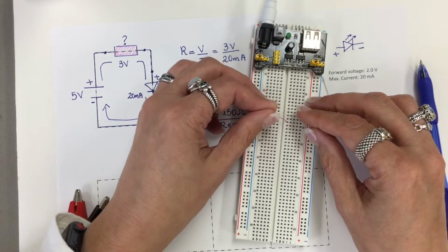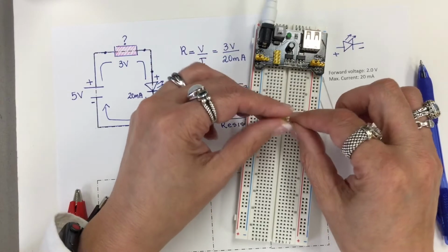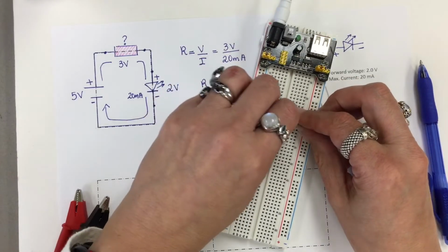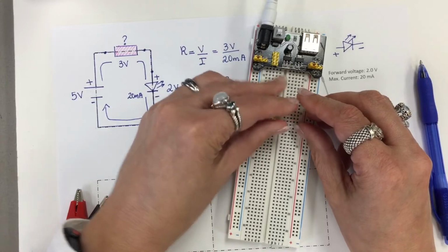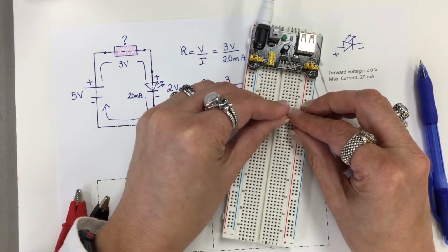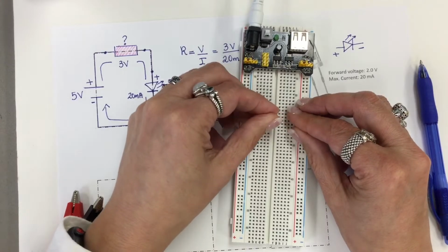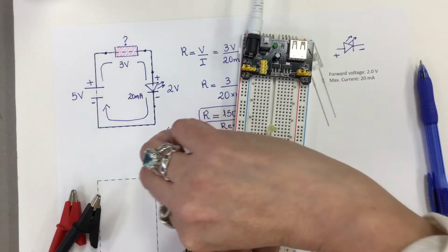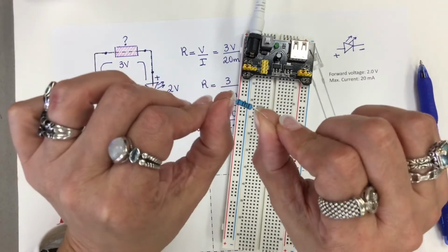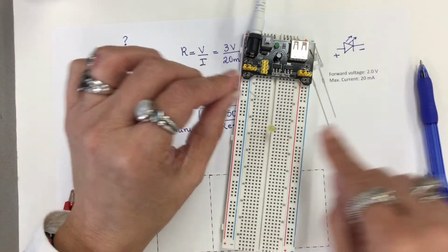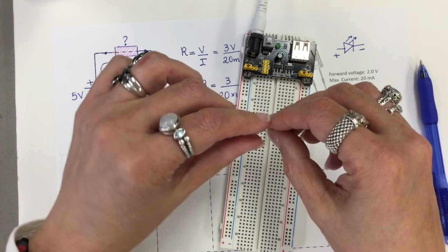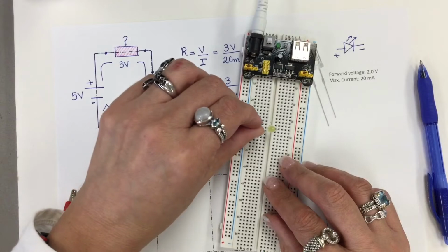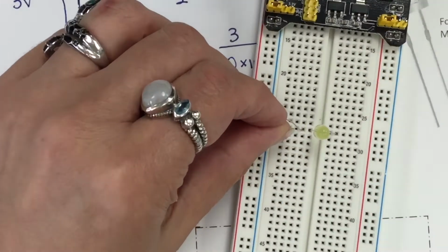So I'm going to connect this LED, open the legs a little bit, and connect on this row and to this row. Okay, you can feel when it's inserted correctly. All right, so it's there. Now my resistor is not polarized, so it doesn't matter which way it goes. If it's going to go to this side or to this side, I'm going to move this guy to the negative. So I'm going to connect. Make sure that you are connecting